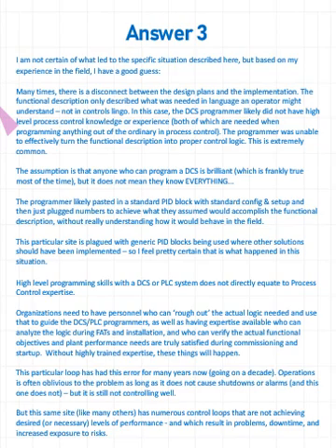Then somebody has to commission it, start it, etc., and they often don't know either. So they're out there trying to find some numbers that kind of work, and they don't really know that the real solution to this is to alter the logic that was programmed. That's an extremely common problem in process control, and I can tell you companies don't want to hear that.